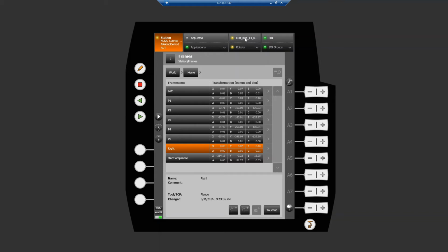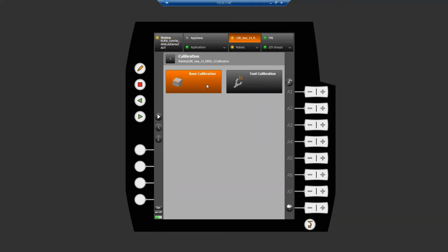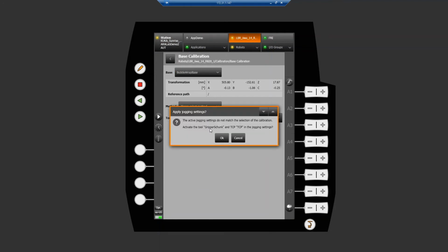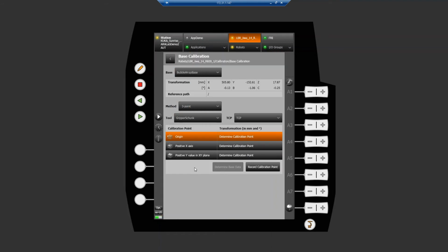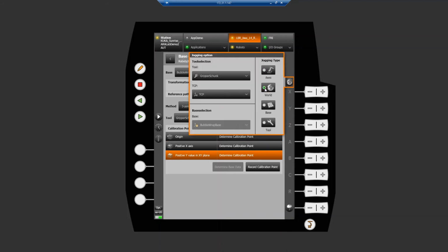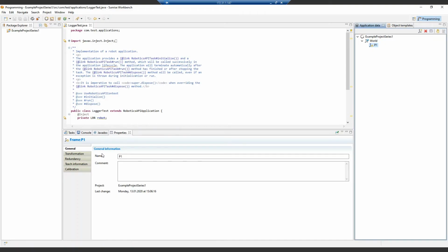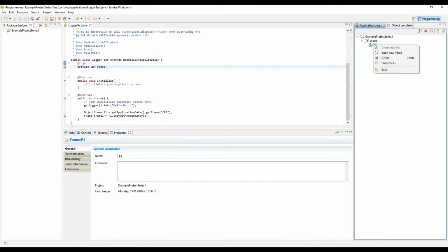and then we can touch it up. If you go to the robot page, what you'll see is that you can also go to calibration, base calibration, and select whatever base you've selected, again by right-clicking, and then in the Sunrise workbench clicking base, and then clicking the method and types, and calibrating the actual origin and the x-axis and the positive y-axis in the xy plane. So that's how you could calibrate a defined base.